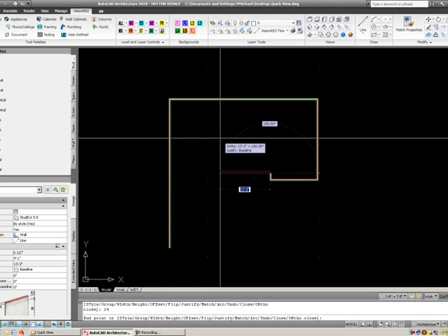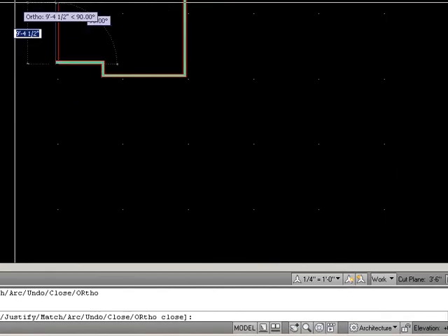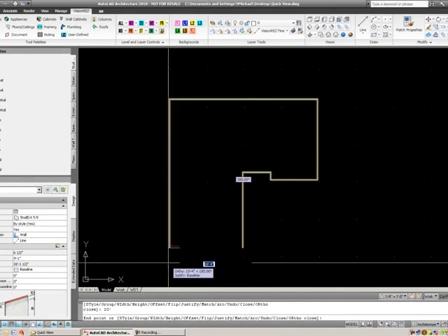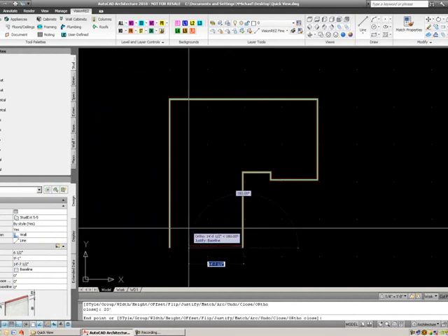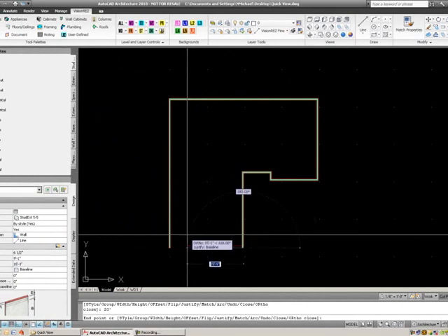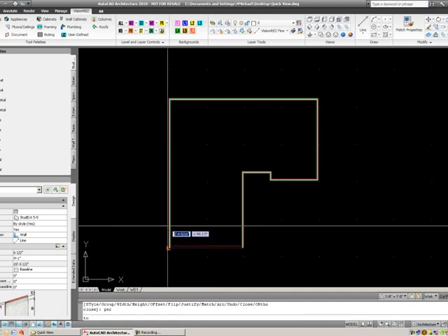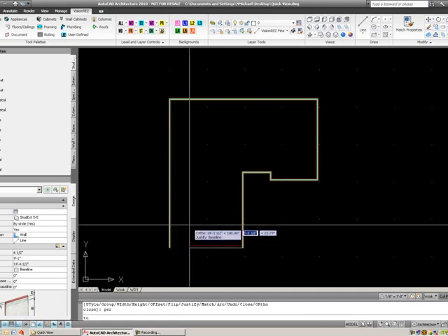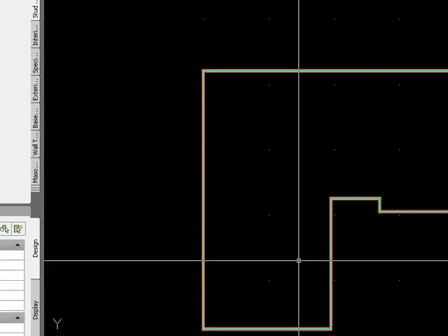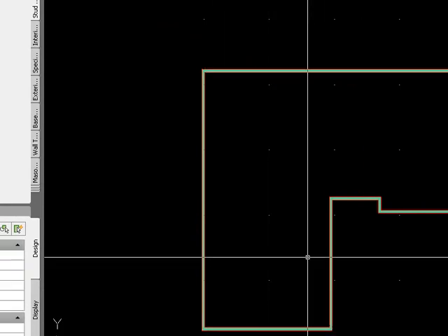Then I'll select a point to the left, draw in that 7 feet, draw a wall down, and I'll select that to be 20 feet. And then this last little bit, I could use my O-snaps and select the endpoint. I could type in perpendicular, and it would draw that wall perpendicular to the last wall. So I have a closed set of exterior walls.